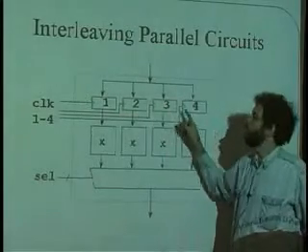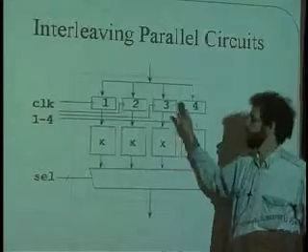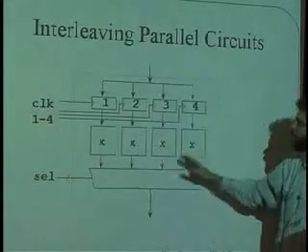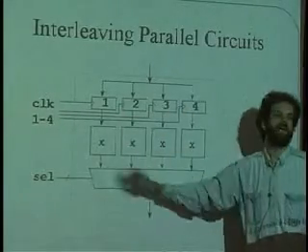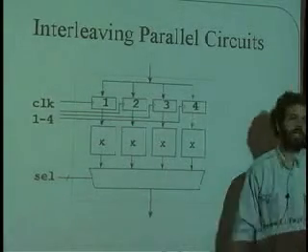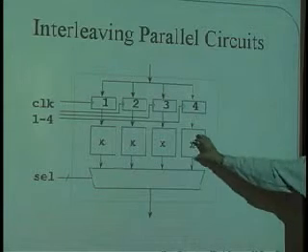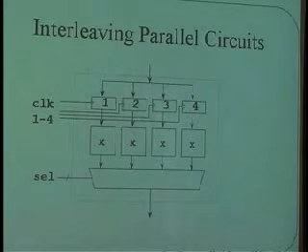And that would be a way of interleaving when the data is sampled by these different registers up here. The units would be over here, and then the selector would be told to sweep around and around, picking up the data. And then the unit as a whole would have a throughput that was 4 times as high as the individual unit here, and a latency that was just the same.